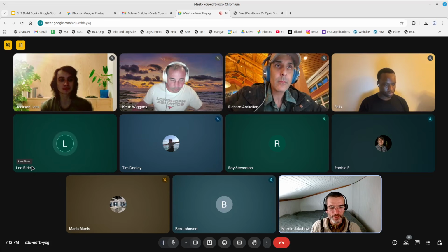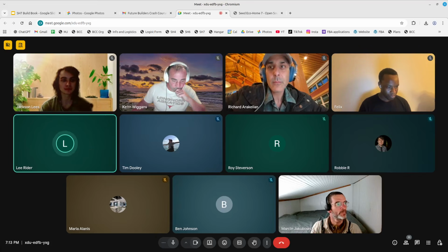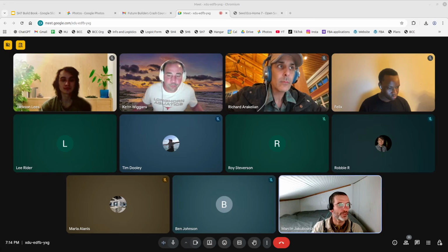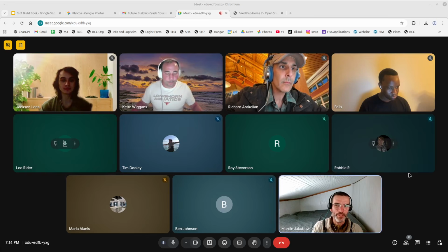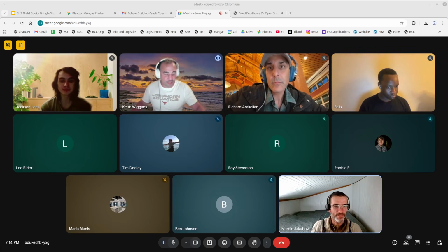Yeah. So when you click the calipers, you just go to length. You click on the edge you want to measure. It gives it to you, and then you get three buttons underneath: reset, save, and close. You just hit save. I haven't been using the save. I was just closing all the time. Oh, that's pretty useful. Has anyone done that too? I'm just doing that on my screen here. Yeah, I've been trying to do that.